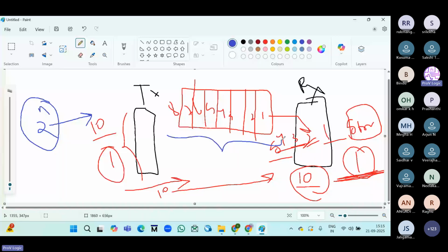Is there any chance of getting a full condition? Of course. For FIFO, we have the empty and full conditions. We always need to check the empty and full condition, because FIFO means first in, first out. It's a sequential write and read operation, whereas RAM and ROM are random access, where we can write data randomly into the memory. But in FIFO, it is sequential, one by one, based on the pointer. Pointer is nothing but location, and location is nothing but address. It starts from the 0th location, then 1, 2, 3, 4, 5, 6.